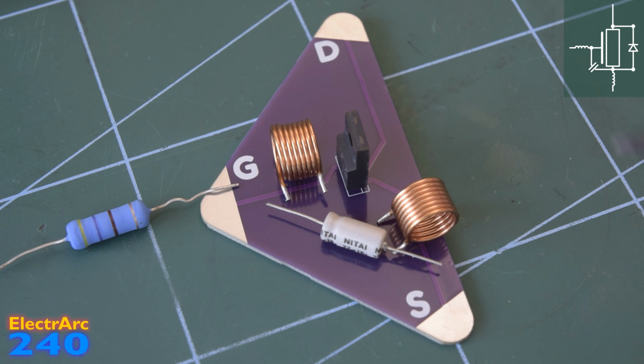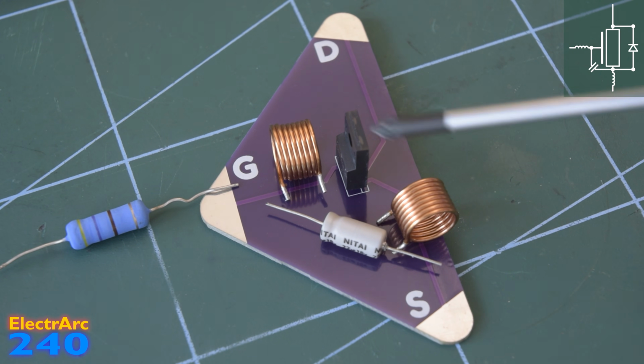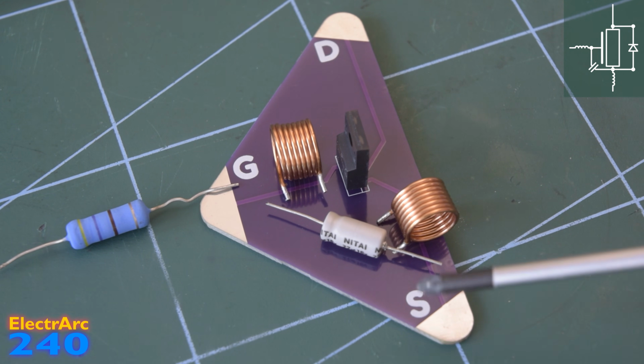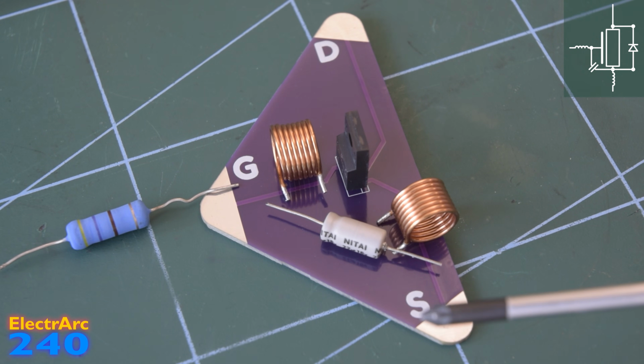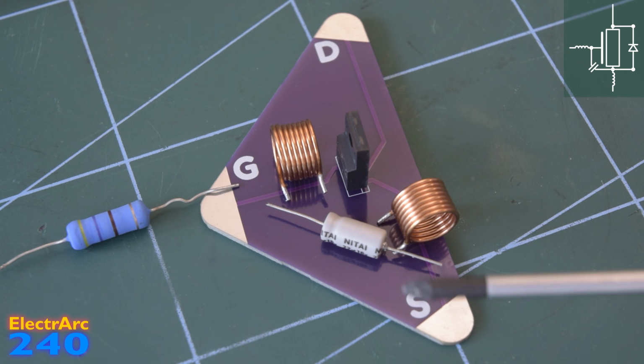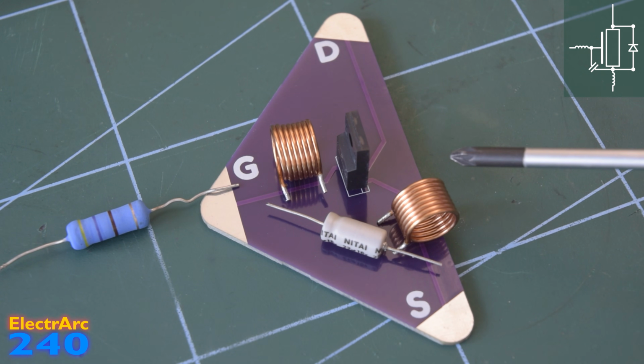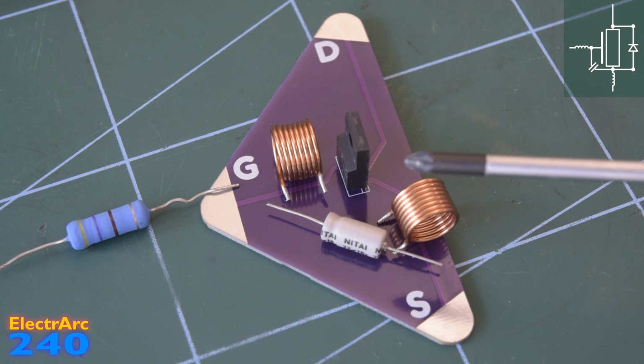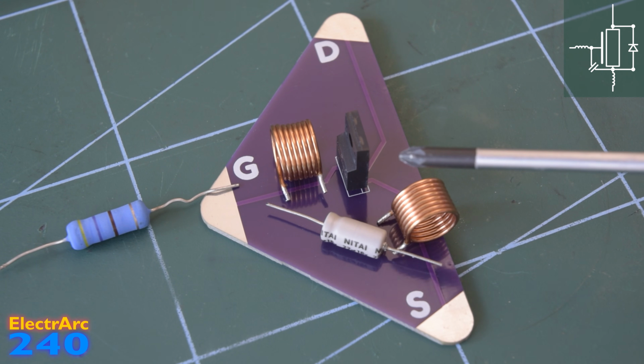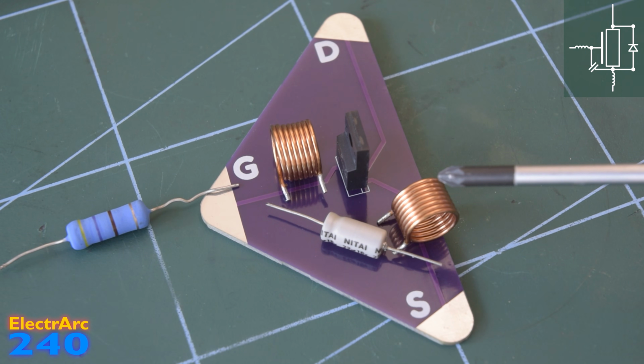And this is because in a 3-pin MOSFET, the source connection is used both for current through the channel from the drain and for driving the gate. Remember, it's the gate-source voltage we need to change, not just the gate. So when we turn our MOSFET on or off, and the current through this inductance suddenly changes from, say, 50 amps to 0 amps, an even bigger voltage than in the gate inductance is going to be generated.